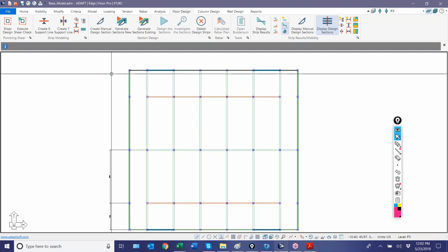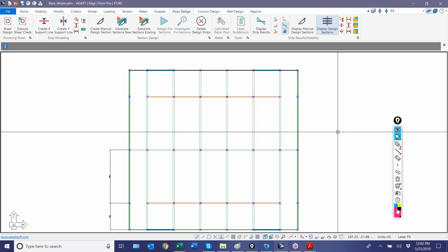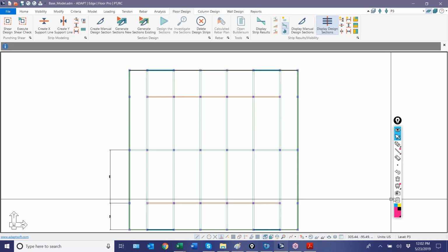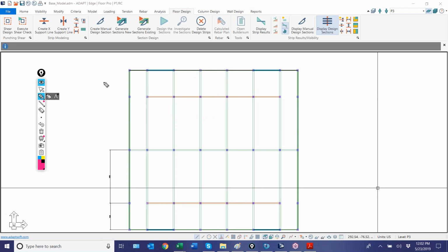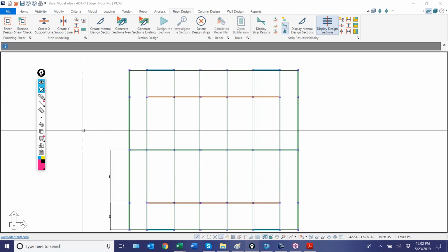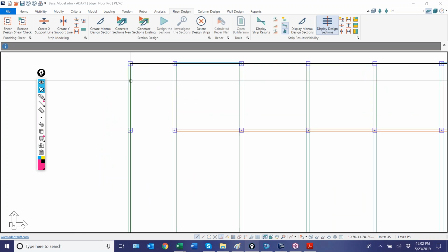I'm going to choose arbitrarily a spacing, a unit strip spacing, for my support lines in this direction. My bays for this slab, let me pull out this marking tool here, dock that over there. So this is 30, and then we have 60, and those are dimensioned down here. This is symmetric about this axis. So I'm going to break this into 10-foot strips.